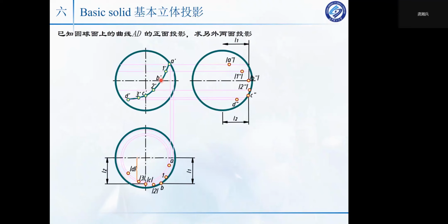From B, the part on the top is visible, and the bottom part is not visible. And from this direction, point C makes this line visible and this line not visible. So you can use point C and point B to tell the visibility of the top part. Point C: the left part is visible.